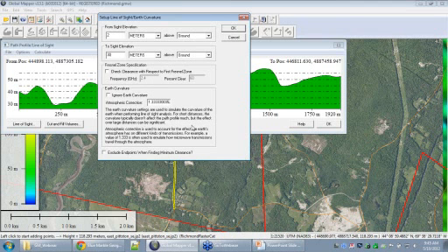We have some options in here for Fresnel zones. That's for those of you working with broadcast transmissions, so things like radio waves, working with Earth curvature. There's a lot of complexity that goes in with that, and there are settings where you're going to be able to use the 4/3 coefficient as well as calculate your Fresnel zones.